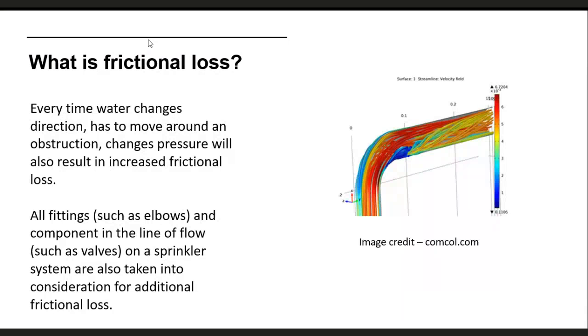Also, the way in which the pipework is actually fitted together is often going to cause more obstructions within the pipe. So again, like a groove coupling, for example, just has that little bump now on the inside of the pipe. Plastic components, again, are going to be a change in internal diameter as we go through different fittings. All of that is going to cause the water to have lots of different currents, which are all going to slow things down, because the best way of doing it is just to have a nice, long, straight piece of pipe.